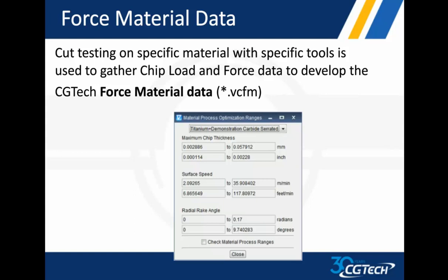I actually was able to see this process happening. It's amazing how sensitive a dynamometer is. It starts to move when the coolant comes on before the cutter ever intersects it. So each line on the graph is each flute intersecting the part.